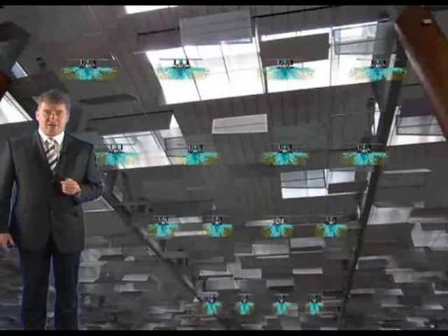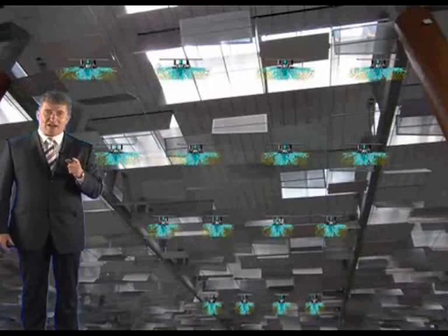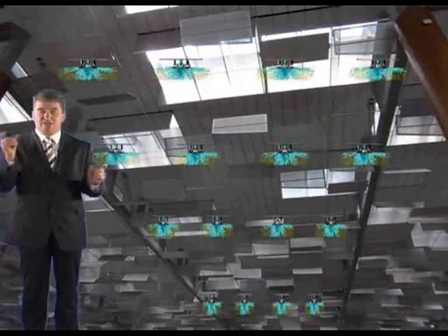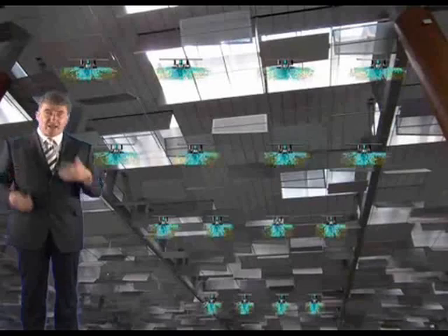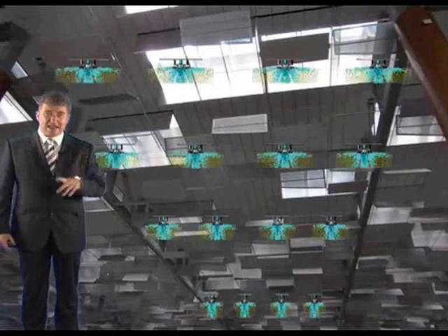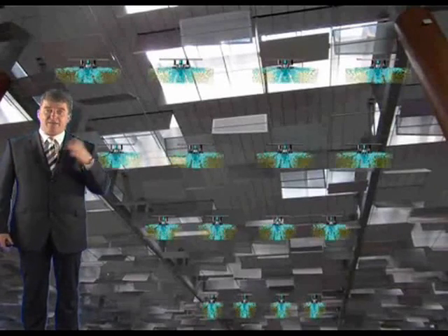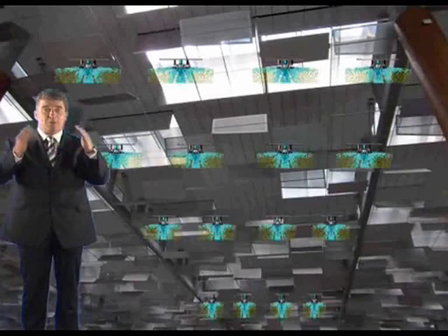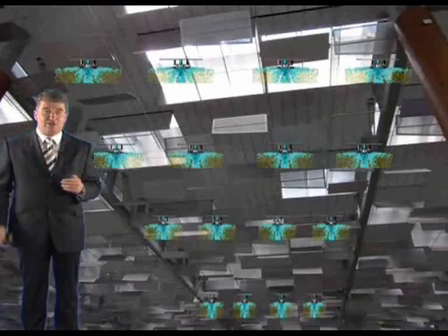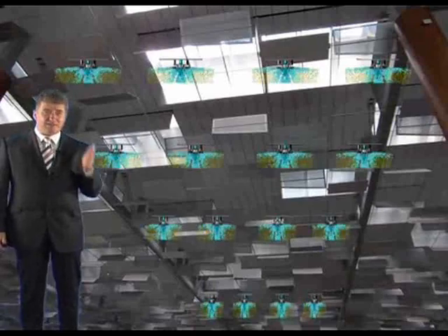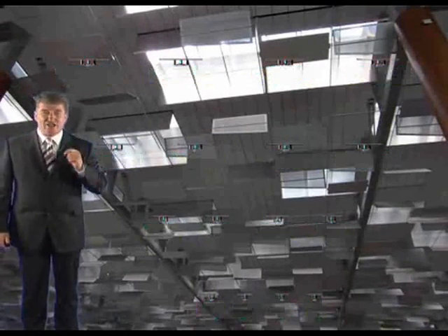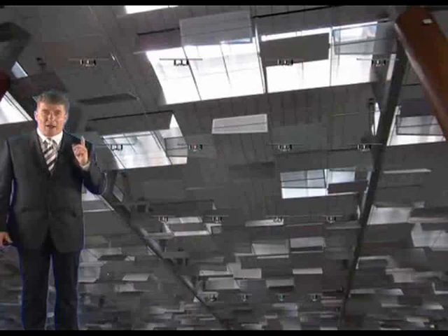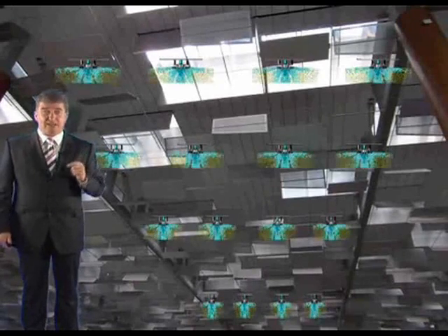Now, another topic for debate is the issue of the interaction between ventilators and sprinklers. The argument is that if the ventilator's open, then this will allow the heat to leave the compartment and affect the sprinkler operation. So if the vent's open, out goes the smoke, it won't set off the sprinklers. Well, experiments have demonstrated that there are no engineering issues raised where both systems are used in the same building.